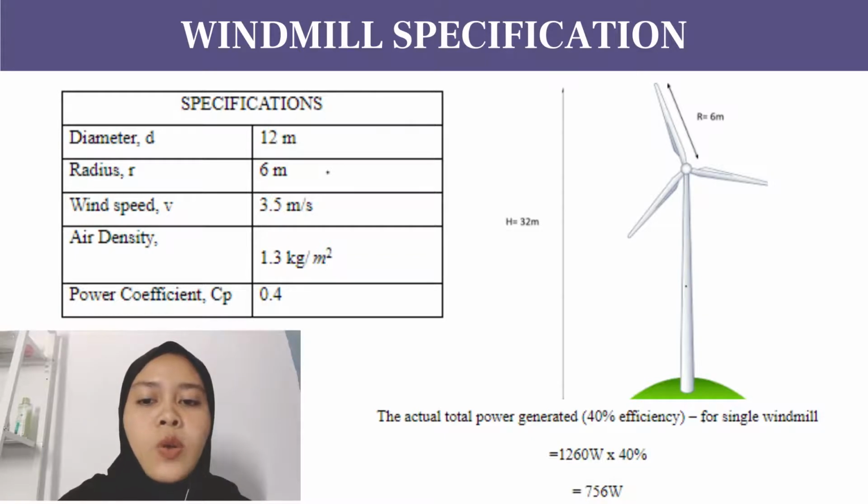In addition, windmills cannot be put too close to each other. Doing so would allow one windmill to slow down the wind speed of another windmill. Although having windmills so far from each other is a waste of ground, usually windmills are placed not less than 5 times the diameter of the rotor apart, without losing power.